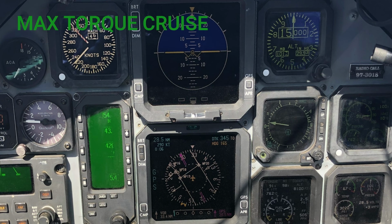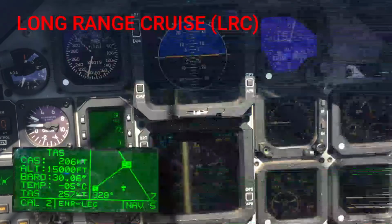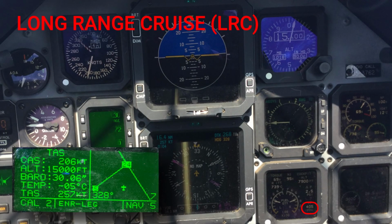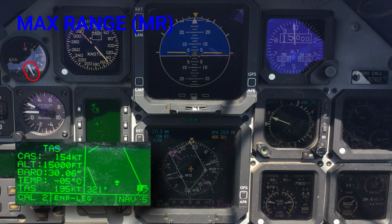As you can see here, the fuel flow is 505 pounds per hour, resulting in a true airspeed of 291 knots. At long-range cruise of 405 pounds per hour, the true airspeed is 257 knots. Max range, flying the triangle, is 300 pounds per hour and 195 knots true.